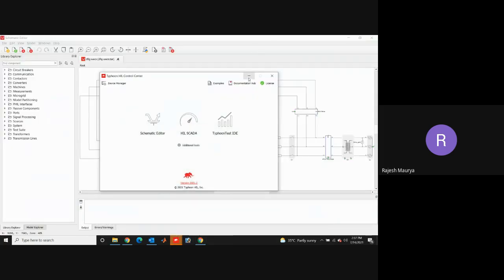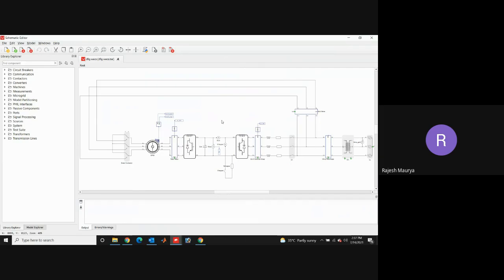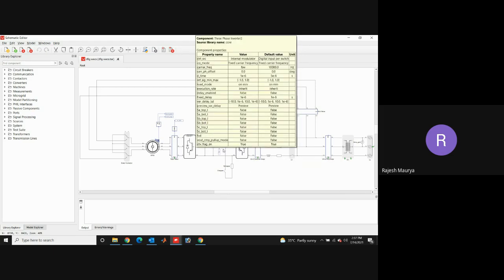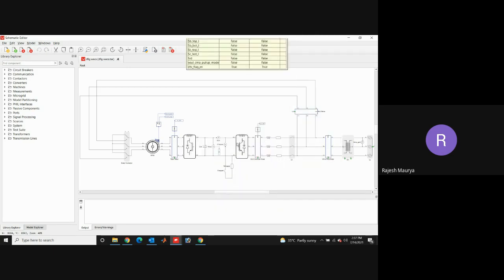Okay, so now we have done the modeling for this plant, and we have taken some goto blocks. Up till this part we have done for this grid connected meter. Now we need to start from this part. We have not given the value for this inductor and resistor up till this grid. Then we'll develop a controller for controlling the DFIG, for providing torque for this DFIG, as well as for giving the PWM for this back-to-back converter. So let's start.